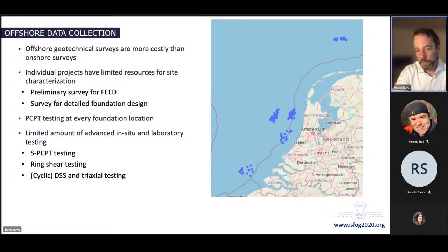Usually for FEED design, we have a fairly limited survey, followed by a more detailed survey once the project gets the go-ahead. In Europe, it's the norm to have a single CPT test at every foundation location, supplemented with selected borehole locations. But even that, we can ask whether that is sufficient. Because if you're working on a site with a lot of lateral variability, even one CPT test per foundation location may not be sufficient if you're putting a jackup down with 4 legs, for instance.